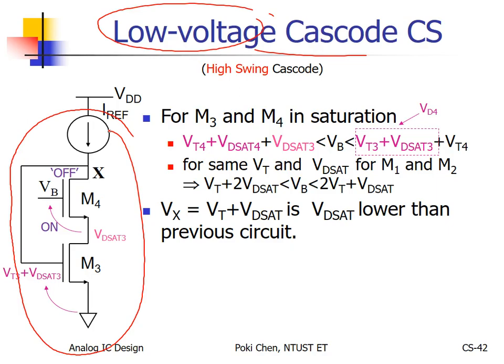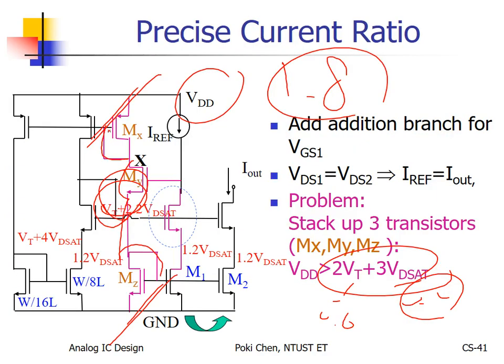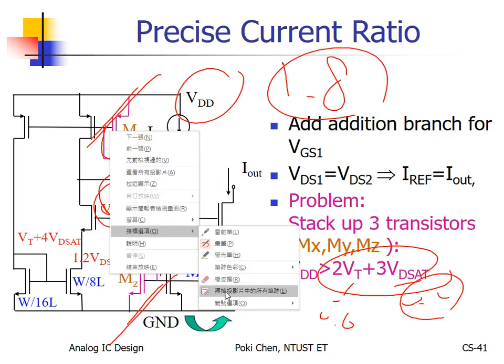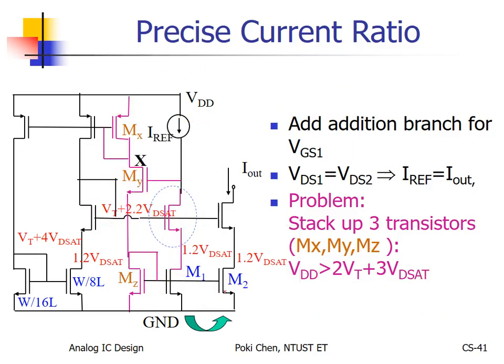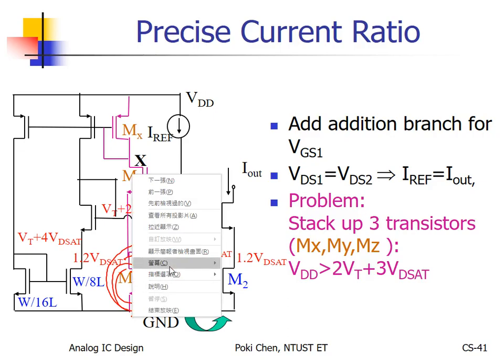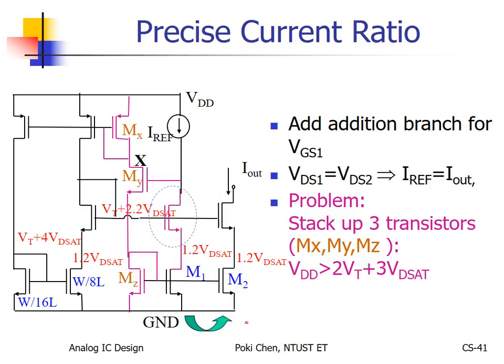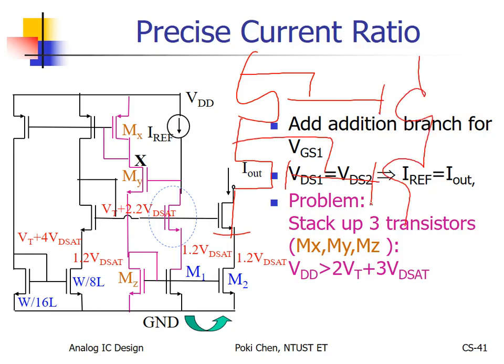Because for regular cascoding, you can see, for example, here, how to generate the bias voltage? You need such kind of diode connection. So usually we have that for cascoding. That is the usual case. I need bias. Who supplies me?